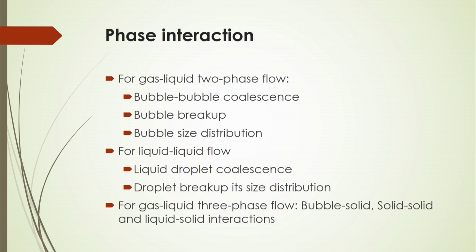Here kerosene is lighter than water, and the kerosene droplets will form just by distribution of energy in the liquid, and the droplet size will change based on interfacial phenomena, like whether there is any physical property change or not. The inertia effect will also act on the droplet surfaces. Then we will discuss what the stable droplet or bubble is.